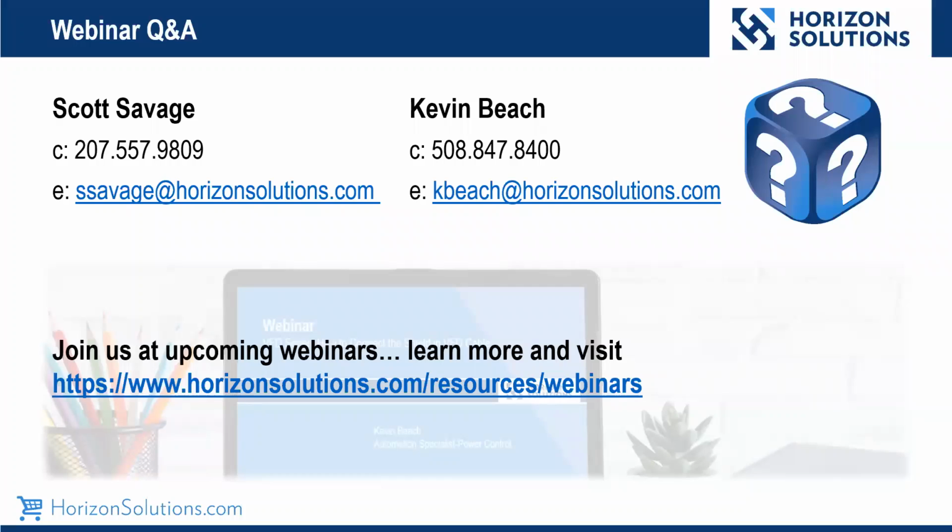Thanks, Scott. Somebody else would like to know, is a bus regulator a standard part of VFDs? Yes, it is. They're in all our drives, though they come in different degrees. The 750 is our premier flagship drive. That comes with a lot more options. You have to put in a lot of characteristics of the resistor itself so that it can actually be a higher performer.